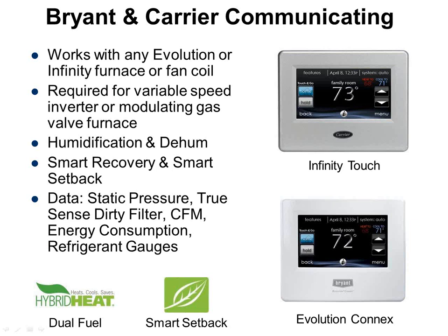So because of that, you can't hook this stat up to just any piece of equipment. The Bryant stats have to be hooked up to an Evolution furnace or an Evolution fan coil. The Carrier ones have to be hooked up to an Infinity furnace or Infinity fan coil, which are the higher tier units that have intelligent communication built into them. And they've had that communication since, I don't even know, like 2004 or something like that. In some cases, those pieces of equipment actually require you to use this communicating stat.